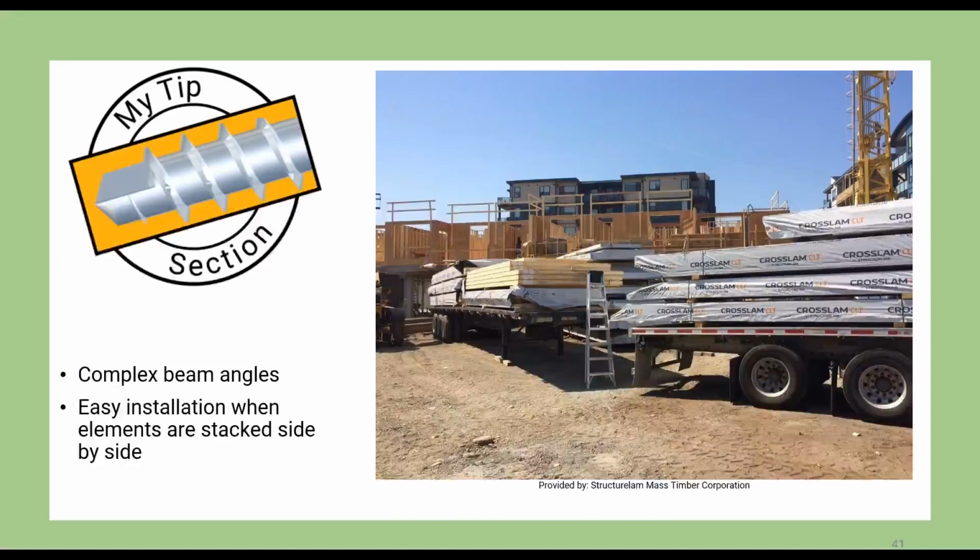My tip: you can use the yoke anchoring system with beams that have complex angles, or beams that are stacked side by side on a truck bed. If you were to lift those beams that are stacked side by side with slings, you would need to separate them a bit, lift them up, wrap around your slings, and then do your lifting. With the yokes, you just go on the ladder, use your self-tapping screws, and then do your lifting. And that's less time consuming.